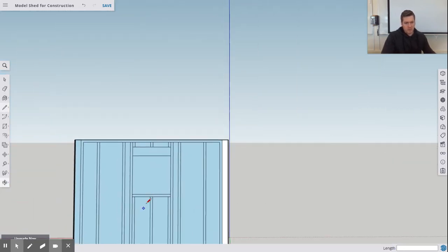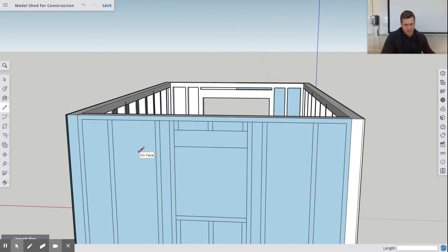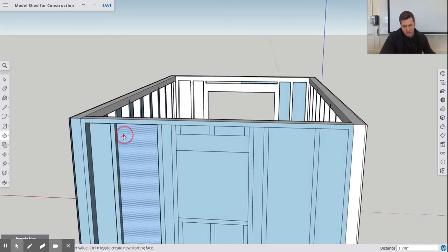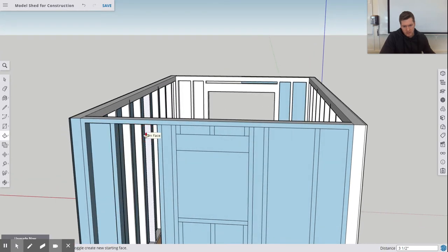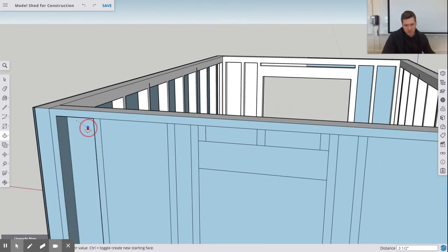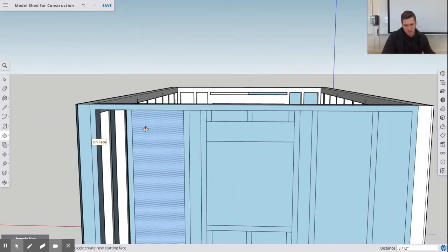Now I can use my push-pull command to push-pull my features through. So if I use the push-pull command underneath the move, underneath offset, it's going to be right there. Push-pull this all the way across until it lines up, hopefully. And let's see if it works for the other ones. There we go, that one. So let's try this one again. Pull this through. Come on, let's do this. Make it work for me. Oh, it worked. There we go. I just didn't see it.